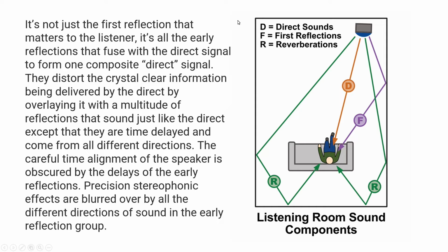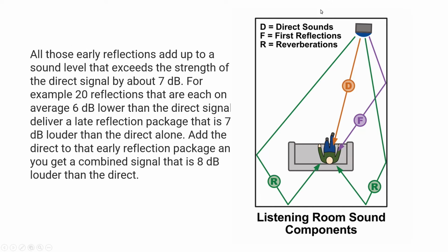And most good budget speakers don't have precise tweeter and midrange time alignment. And also when you're working with 24 decibel crossovers, your overlap is really small, and normally you don't hear that. This is one reason why it's not important at any cost to have a digital crossover and this delay adjustment. But many audiophiles complain and talk in forums that it is super critical. In reality, not.